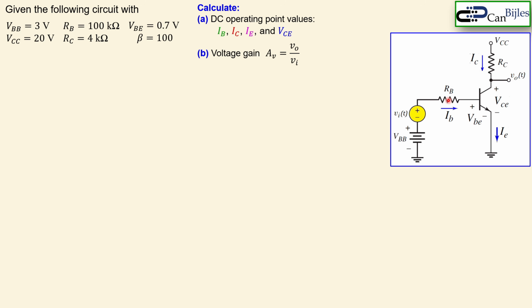You see three arrows here, IC, IB and IE. Those are the total values of the AC and the DC quantities together. That's why we have a capital letter and a small letter for a subscript. So we have the IC, IB and IE in the same configuration, also for the collector emitter and the base emitter voltages.